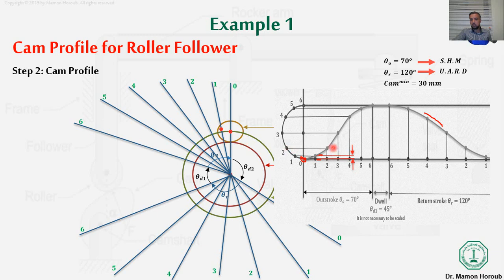And this distance, assuming for example 2 millimeters or 3 millimeters, should be the same distance that the system raised from the first point until the point that I need to draw. So the distance between the green circle and the red dot should equal the distance between the profile of the displacement diagram and the theta axis.